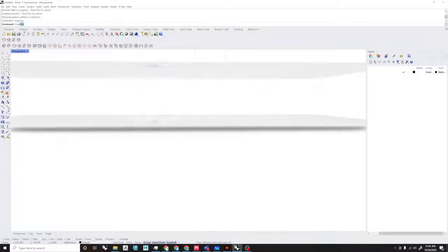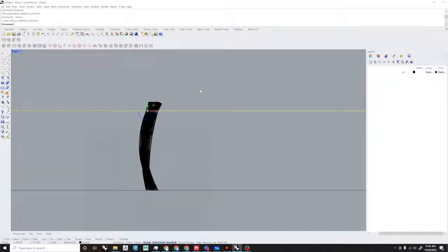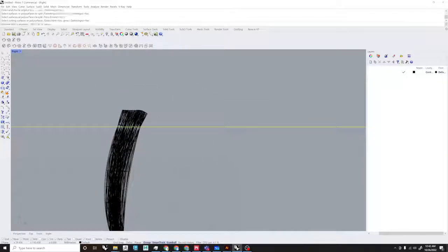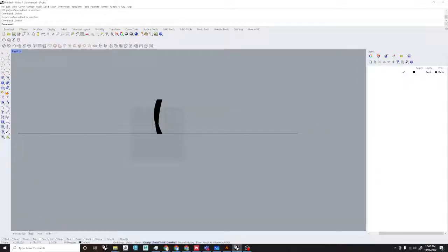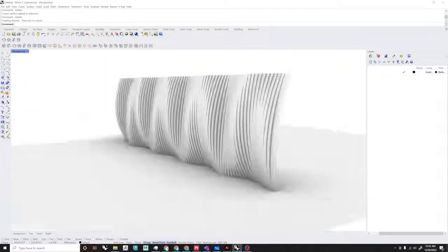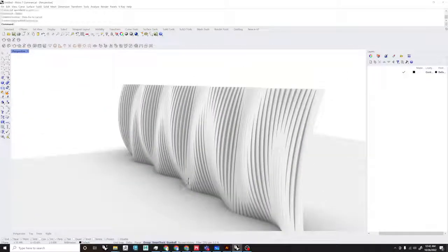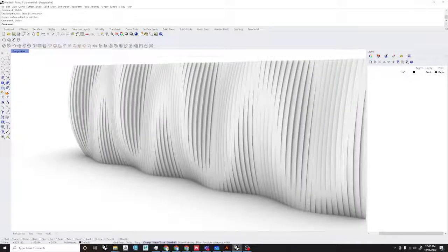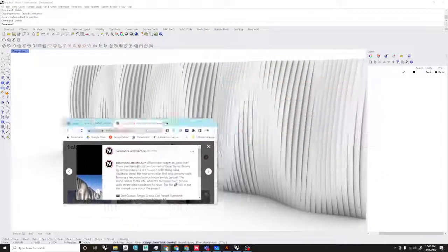Now it comes in grouped. I group it always. So you have to go into right view. Delete all these and then do another Boolean split. Delete that. And now you've got flat edges. And now you have this. Perfect. Well, it's not perfect, but it is close to what will be represented as this. Yeah, it's pretty close actually.